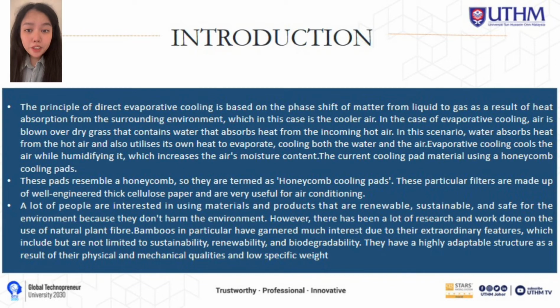Another important fact about evaporative cooling is that it consumes very small power. Only a fan is needed to drive it in the case of a fan pad system. If water circulation is necessary, then a water pump is also driven by the power, but both of them consume less power than other traditional cooling systems. Air is cooled by passing through a wetted surface, which is the cooling pad, and then loses a certain amount of sensible heat, which increases an equal amount of latent heat of water vapor.